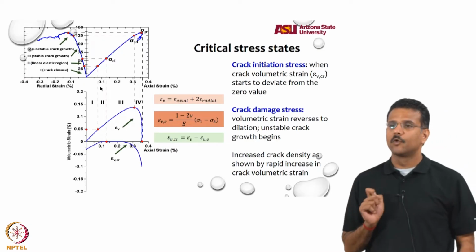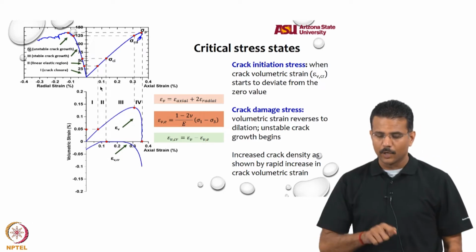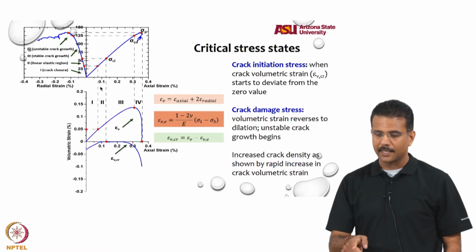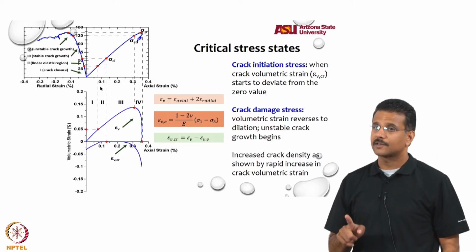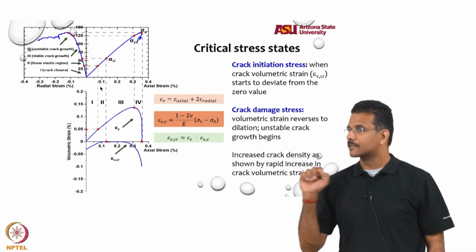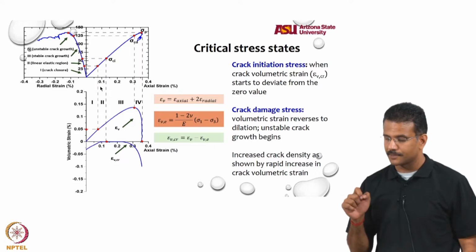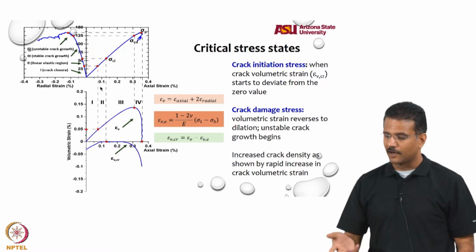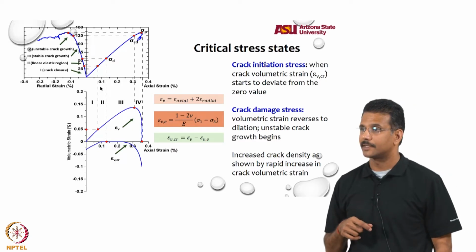Now, slightly different structural aspects to think of when you design this mix. What I have shown in the picture on the left top are the stress strain curves, marking significant points on the stress strain curve based on the strain relationships. What I have in the bottom curve are the axial strain versus volumetric strain, so the response of axial versus volumetric strain. Volumetric strain is nothing but the axial strain plus twice the radial strain, and you can get it from simple transformation using Poisson's ratio and the principal stresses sigma 1 and sigma 3.